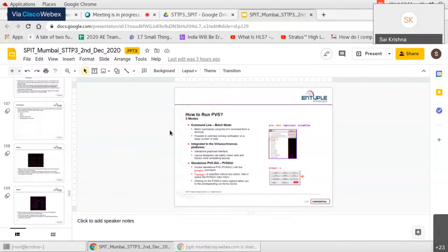Once everything is clear, you will come to routing. So after routing is done, again timing, area, power, congestion. If there are violations, post route optimization. So only when all the violations are cleared, you are free to go to timing and power sign off.